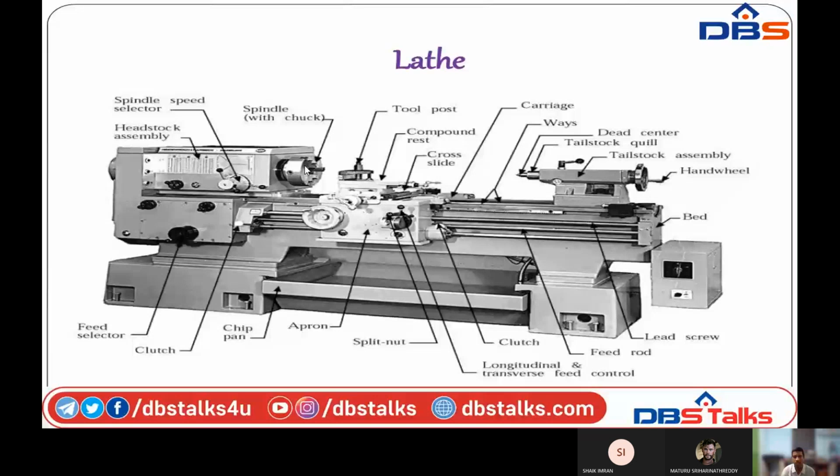Next, I am showing the tailstock to you. The tailstock is placed on the bed here. The right side part is the tailstock. It is also just a support for the component. In this, I am placing a tool. It is always at a stationary point, but it is used in some operations like drilling and reaming. Next, after the headstock and tailstock, the carriage. The center part is the carriage. Carriage consists of cross slide and compound rest. The cross slide moves in a reciprocating direction, like upward and downward.